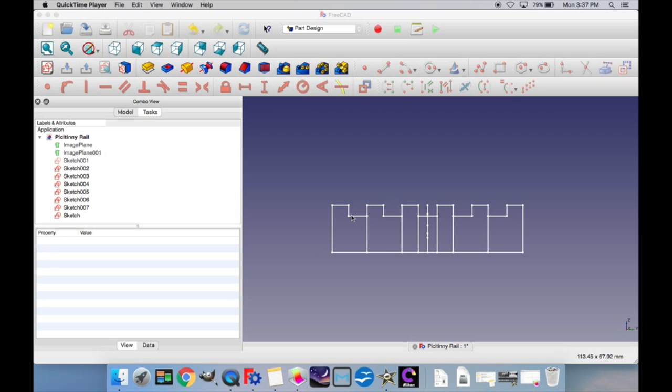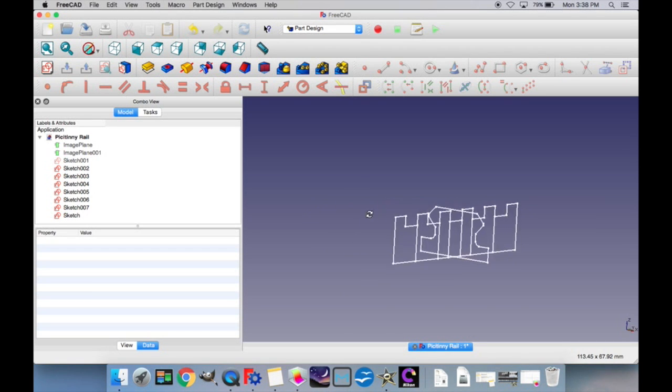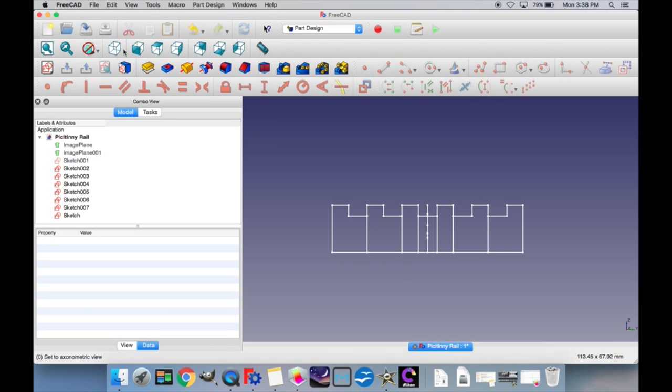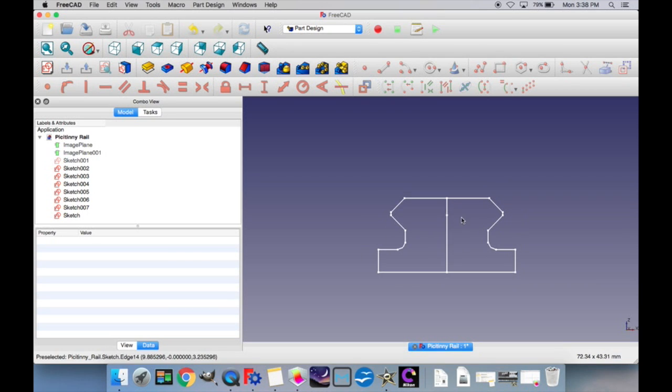It's just what I'm doing for the example here to show that you can save time by just doing the first part of a pattern. So now that the side view is completed, when we pad it, we can use symmetrical to plane in order to extend it in both directions. But we need to know how long the side view needs to be in this direction, and in order to get it to extend past to the edge of the front view here.